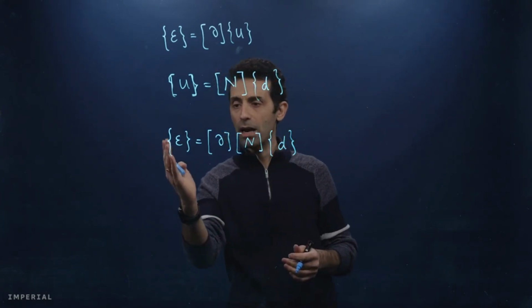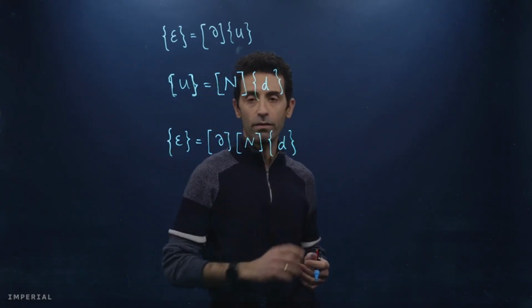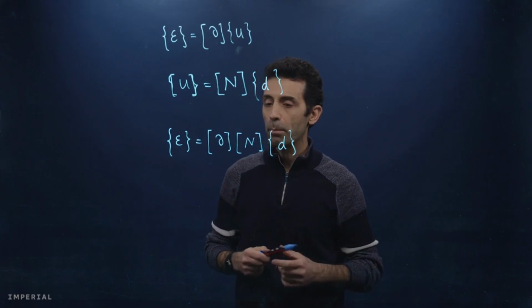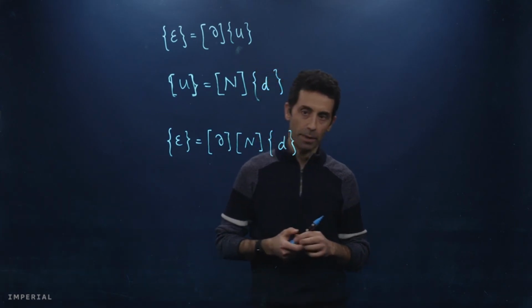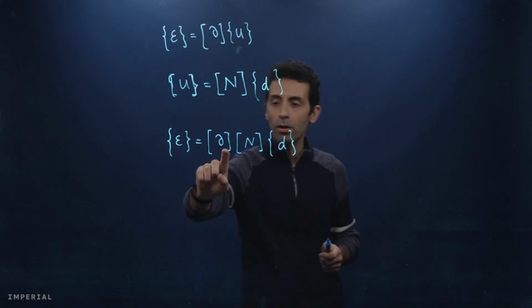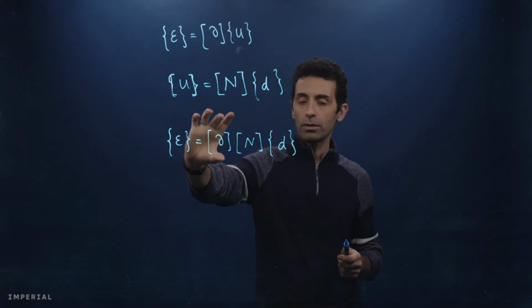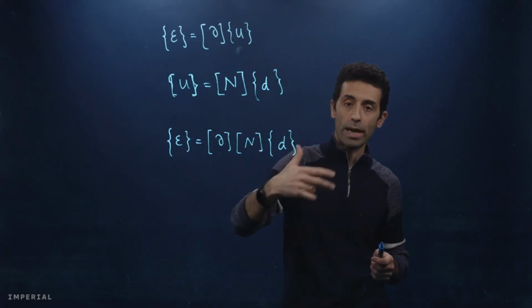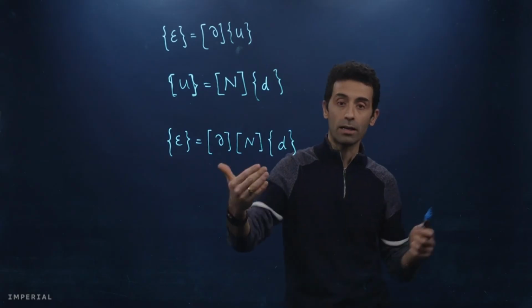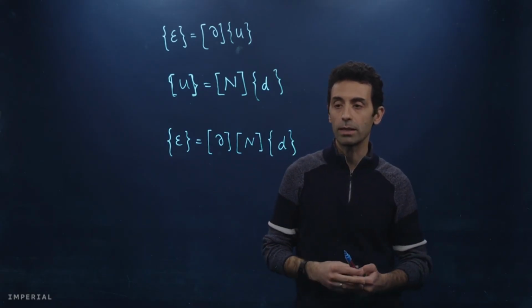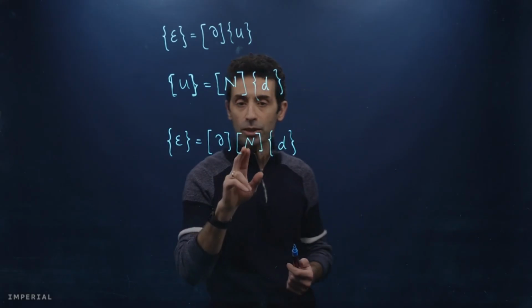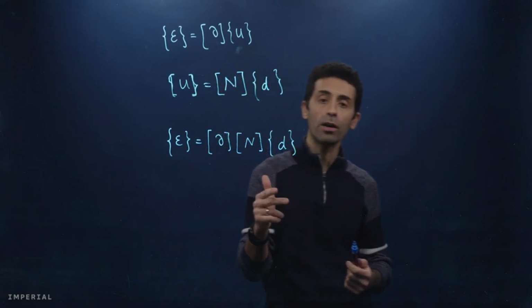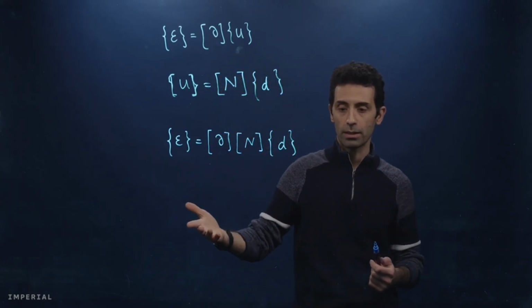So it seems that now we can find the strain from the vector of nodal displacements, but there is a problem here. If you remember, all these derivatives that go into this matrix, they were with respect to x, y, and z. Hence, they were in the Cartesian coordinate system, right? But our shape functions, they are in the natural coordinate system.